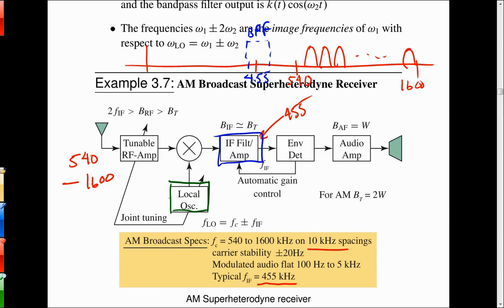You start at a 70 megahertz intermediate frequency and you're going to move it up to a higher one. The customer provides you with a 70 megahertz IF already. That's the way a lot of satellite systems work. But we're talking receiver, so in the receiver it's definitely safe to say you move it down. But there can be different reasons you might need to move it up. So the difference is what we're after.